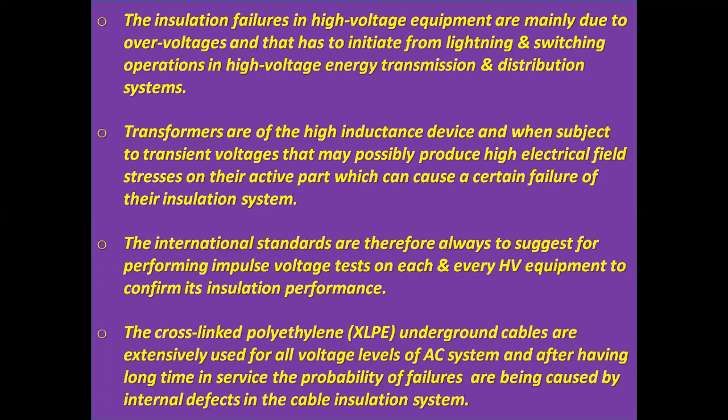Transformers are high inductance devices, and when subject to transient voltages may produce high electrical field stresses on their active part, which can cause failure of their insulation system. The international standards therefore suggest performing impulse voltage tests on each and every HV equipment to confirm its insulation performance.